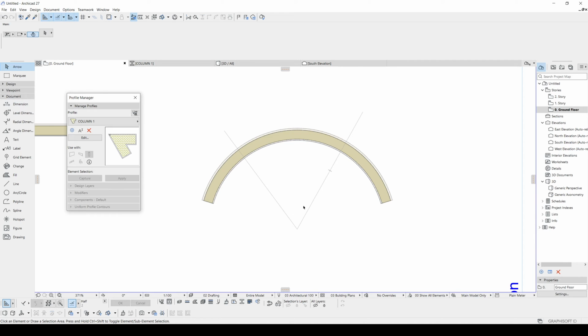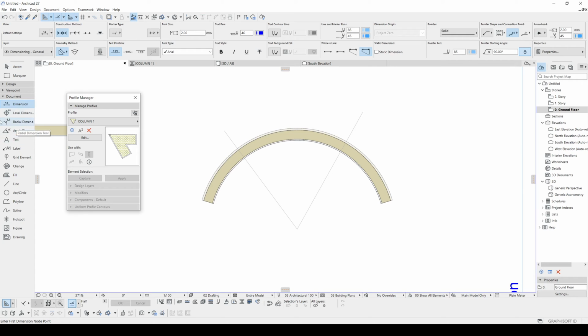Well, if you want to see some dimension, you will go to dimension under the document, and after that, for the geometry method, we will click this arc length, and we will click this edge, intersection point. This is the starting corner, continue, and this is the end corner. When you finish, right click and click OK. Offset the dimension and place.